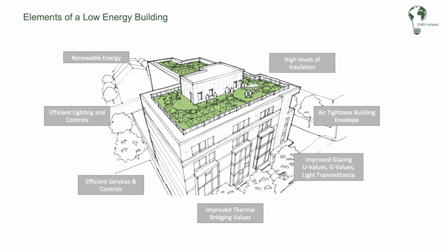As I said, they are the common principles that are going into all these buildings at the moment. So insulation, airtightness, glazing orientation, efficient systems, and renewable energy. Renewable energy is actually the last piece of that jigsaw. You have to get all those passive features, passive solar design, all those elements right first time. That really brings down the demand. The second part is the energy consumption, so your efficient systems. And then at the very end, renewables. There's no point building a leaky, inefficient building and then spending hundreds of thousands on renewables to try and fix it. It just doesn't work.